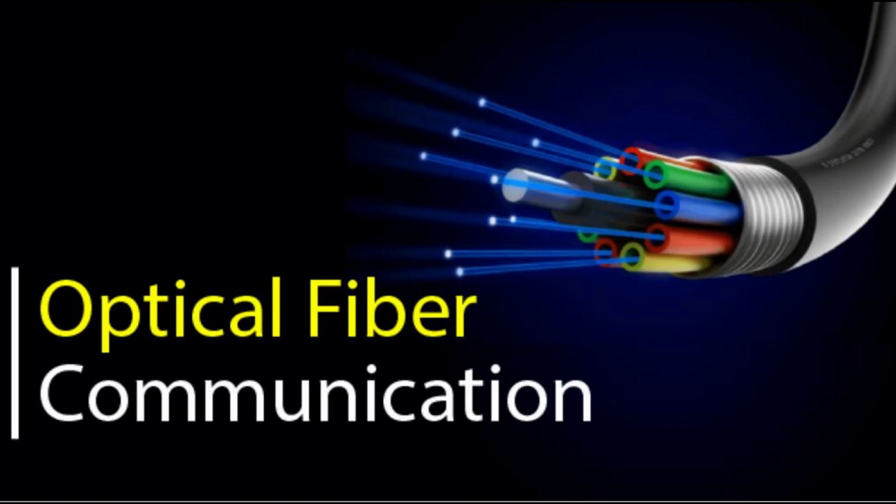Fiber optic cables are used mainly for their advantages over copper cables. Advantages include the following. They support higher bandwidth capacities. Light can travel further without needing as much of a signal boost. They are less susceptible to interference, such as electromagnetic interference. They can be submerged in water. Fiber optic cables are stronger, thinner and lighter than copper wire cables. They do not need to be maintained or replaced as frequently.